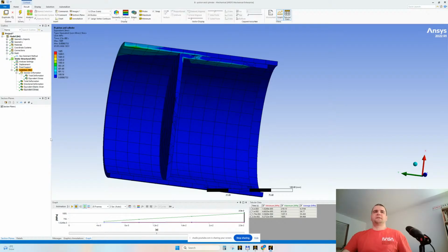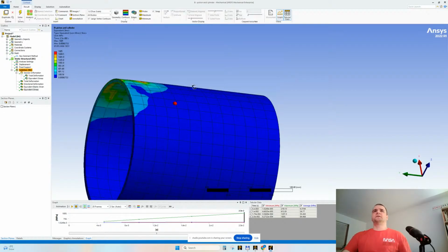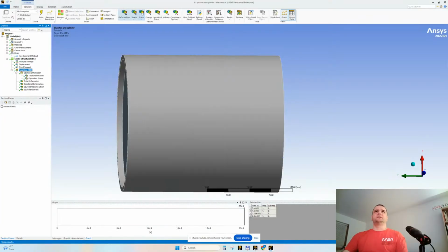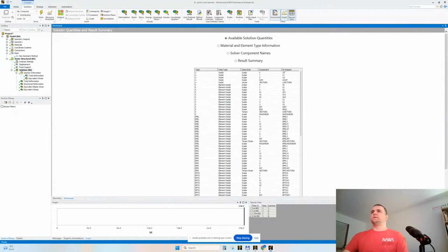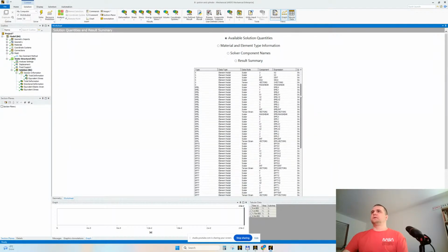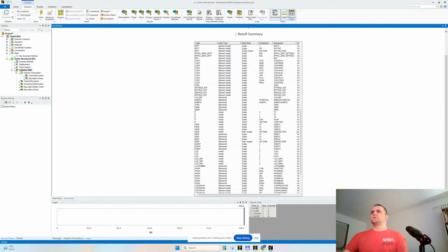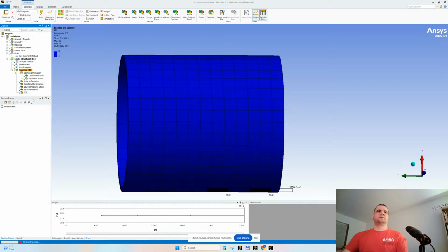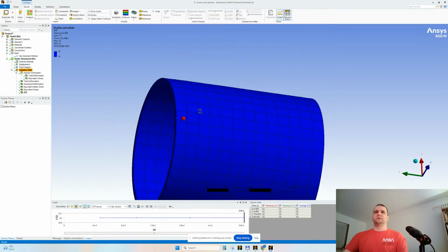All right, so we're investigating if heat dissipated. How can we see heat? Heat usually is seen by accessing worksheet. And here we're looking for BFE. It's not an item called temperature, but it's called BFE, which measures temperature. BFE, look, this one, all right? So if you drag and drop, you can see here already temperature, the output unit, all right? Create user-defined results, right-click, evaluate all results. Yeah, no heat.